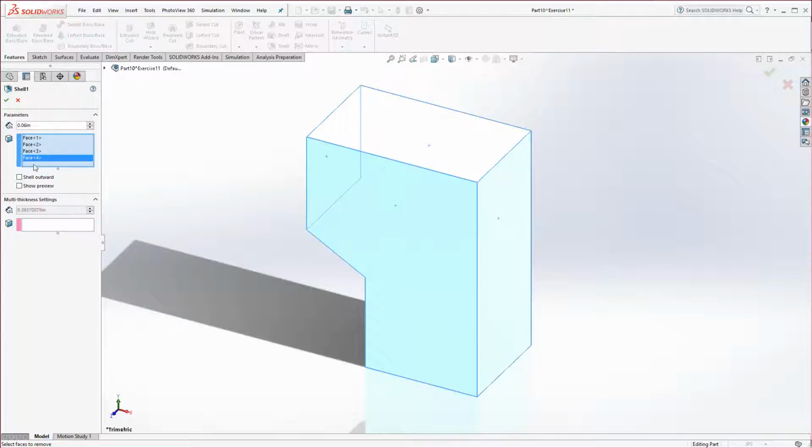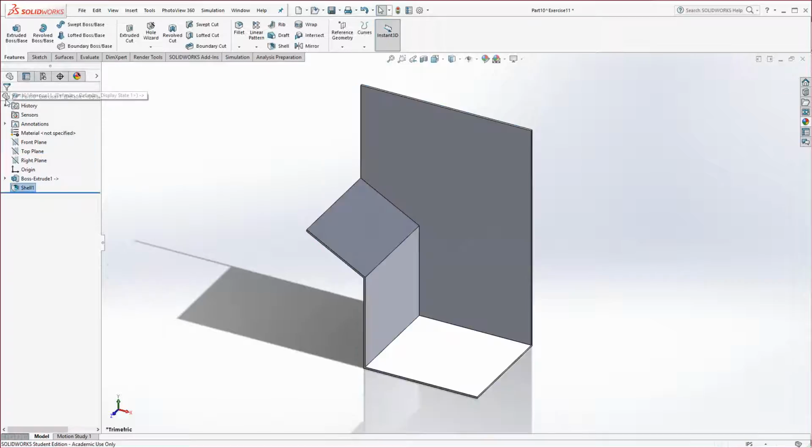We could go ahead and, one last thing, select Shell Outward. This will make our sheet metal on the outside of this volume, so that will fit over the cover, or fit over the gears and that casting that we had copied the edges from. So that's why we're doing shell outward. Hit the green check mark, and we're left with this.